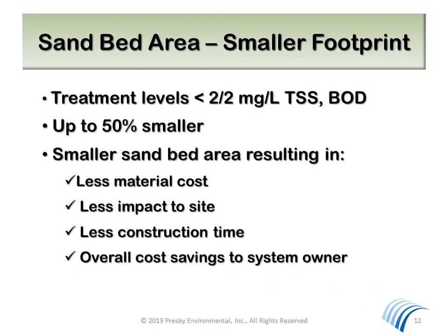Advanced Enviroseptic treatment systems have passed the stringent requirements of NSF 40 Class 1 protocol. This helps to justify up to and sometimes more than a 50% reduction in treatment area sizes as compared with traditional pipe and stone fields. Your state-specific design manual will provide the necessary sizing for your area. Our smaller treatment system results in less overall cost to the consumer, while still offering an environmentally friendly system.